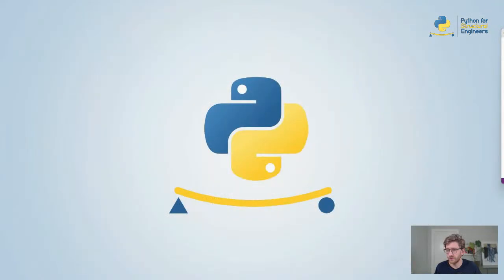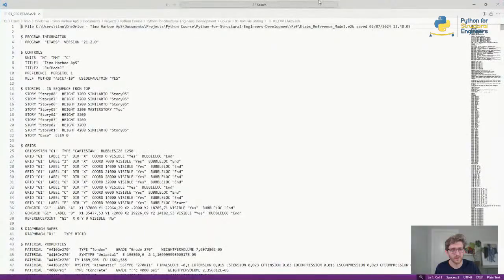I'm just going to close these here and then find this one over here. So this is an example from ETABS. So let's say that you have made an ETABS model. So you've designed a tower, and you have received some information from your geotechnical engineer that you need to update these spring stiffnesses. And in your initial model, you just have the same spring stiffness for all the springs, but now you need to vary all the springs. And your geotechnical engineer is going to come with new results next week and the week after. Like, you're iterating to find the right values for your spring stiffnesses.